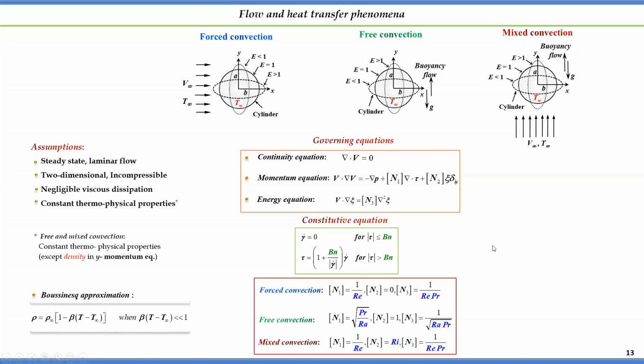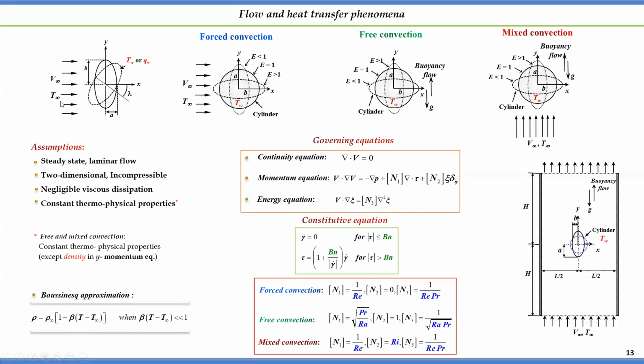Similarly, we are also interested in studying the orientation effect of this object when it comes across the flow of Bingham plastic fluids. These fluids don't have any boundary; they are flowing unboundedly. But if you confine the flow by placing this cylinder between two parallel plates, that means in a channel, then you can also observe what kind of different behavior this fluid will experience.